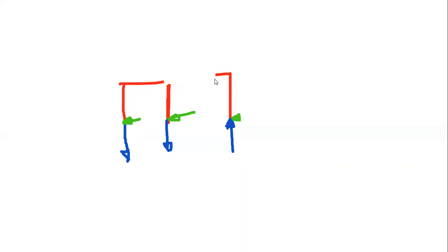Suppose for this particular frame we have to find out the centroidal axis, the CG. So what is step number one? We have to find out the centroid, the x bar. The CG distance we have to find out from this left column. So we will consider the frame of reference: this will be the y-axis and this will be our x-axis.